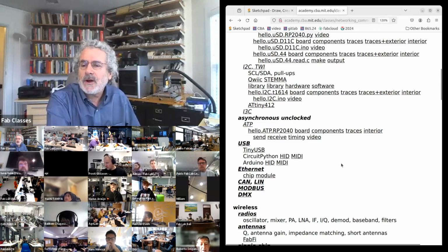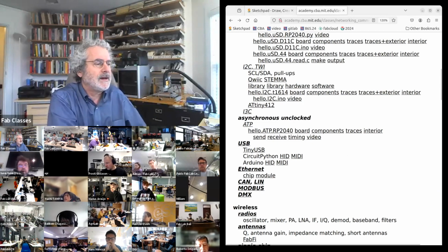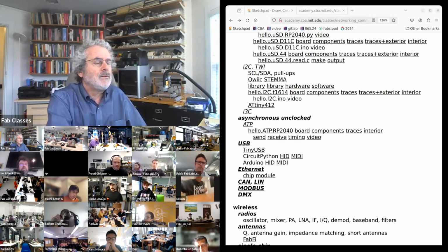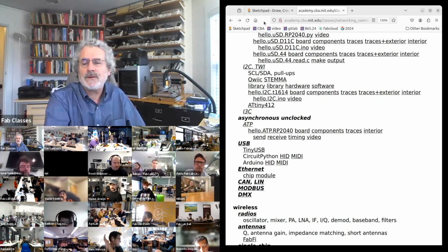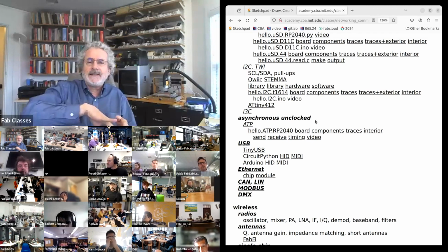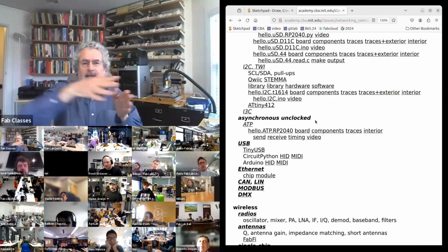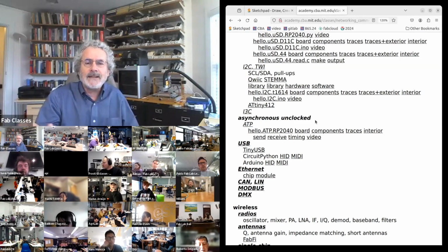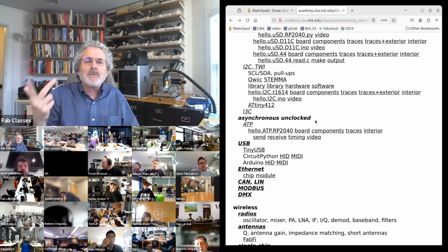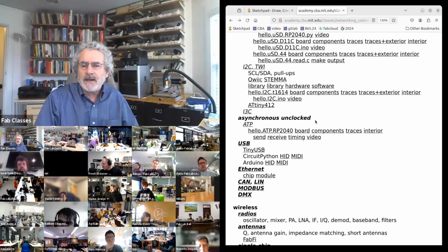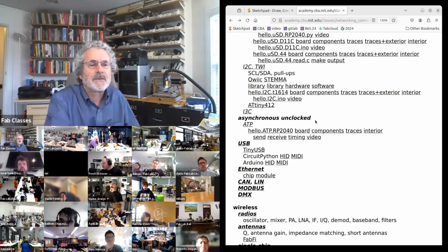yeah, there's a note from Ricardo about, and I don't really talk about this, long cables. When you have a long cable, there's a lot of capacitance and inductance, and it can take a long time to charge. And as the signal travels down it, you can get reflections. And so at high data rates, much more thought goes into how you drive them and how you terminate them. It's not an issue for this size of things in front of you.